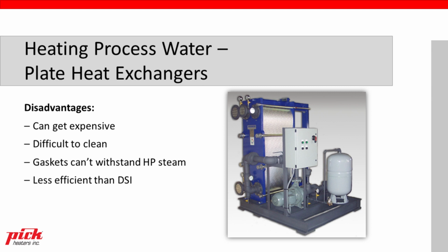Gaskets that are used can't withstand high pressure steam. I have seen them in the field where there's a shroud put over the plate heat exchanger because they're leaking due to the use of high pressure steam. High pressure steam comes with its disadvantages to these gaskets, which just don't withstand those pressures and temperatures. And then, of course, you're only using, again, the latent heat energy in the steam, so they're less efficient than direct steam injection heaters.